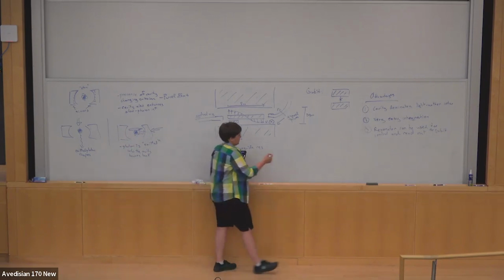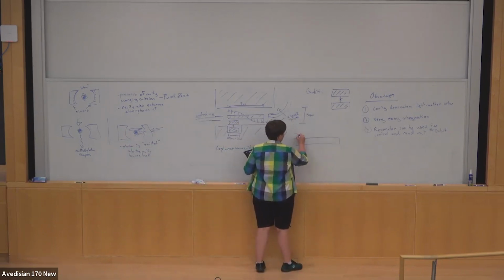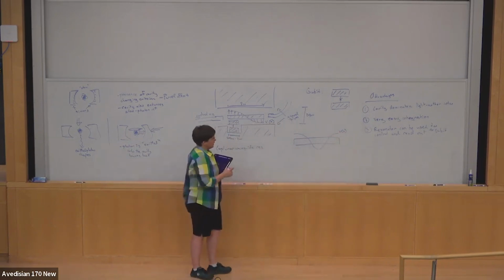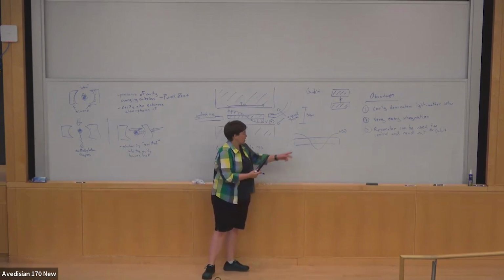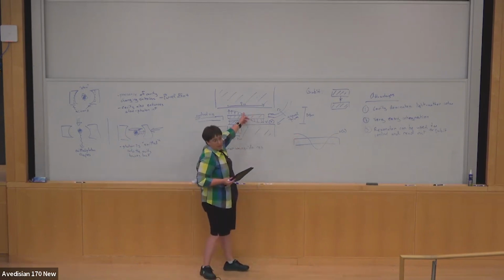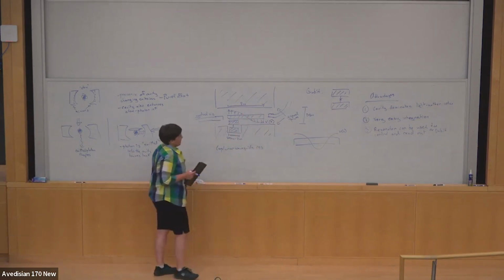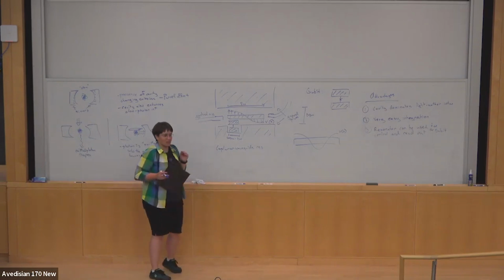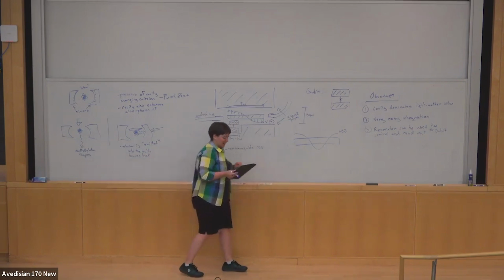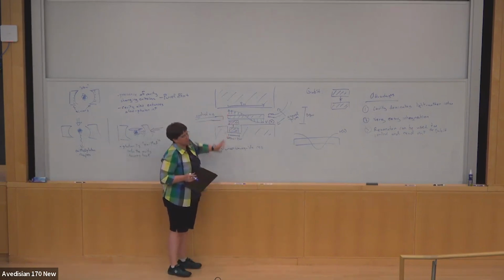If we're going to end up wanting the frequency of the cavity near the qubit frequency, not too far away, and you want this second harmonic mode to be at 7 gigahertz, as opposed to that one at 7 gigahertz, you have to make it twice as big. And let me tell you, it's painful to make 12 millimeter long resonators and fit them onto a chip. They take up so much space. And so this has turned out to be the more standard design.